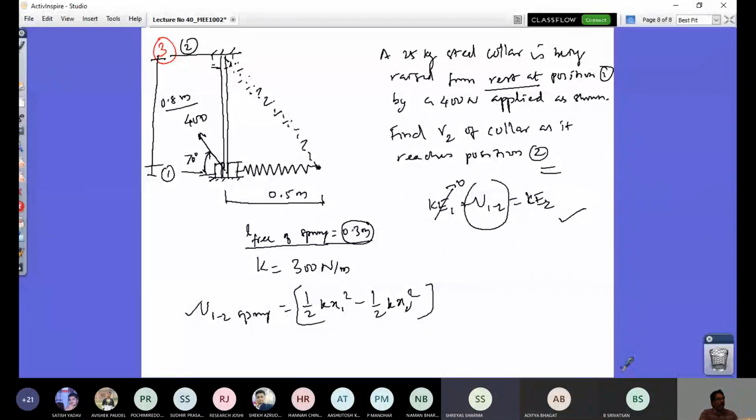If spring force is there, is the system conservative or non-conservative? Conservative system, because a spring is a conservative system. There is no loss of energy in a spring, right? It is not a damper. There are materials like rubber tire, which is a viscoelastic material, so you have to model that as a mathematical model. You'll use spring and damper. The damper represents an energy dissipating setup, whereas the spring is an energy storing or energy expending system, which is a conservative system, right?